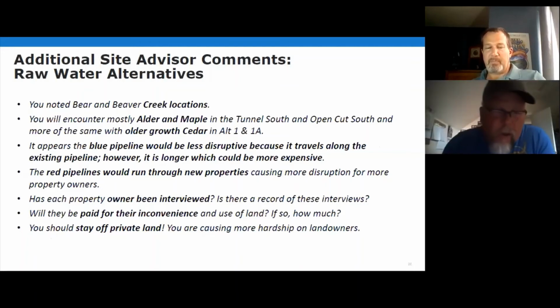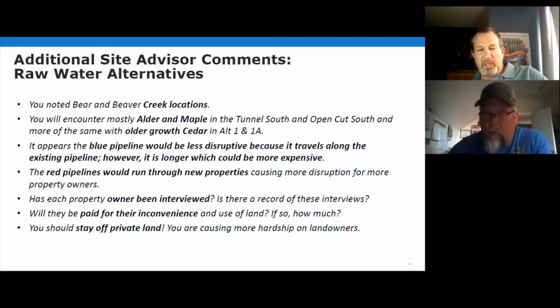You talk about the aquifer, but there's actually two aquifers down there. Is that not correct? You're talking the shallow aquifer that's up on top? Yep, the shallow Troutdale and the deep Troutdale aquifer. So we believe with the Walters well, that's the only shallow well that's in the shallow aquifer. Everybody else is down in the deeper aquifer. As far as the records that our geotech has found to date, yes, there are two aquifers.